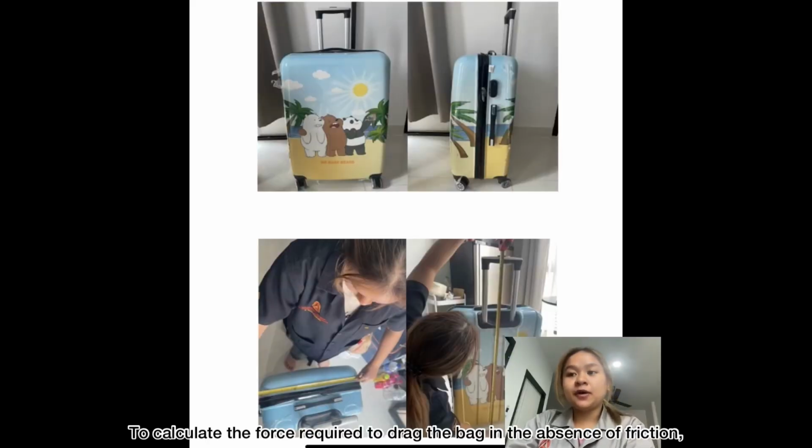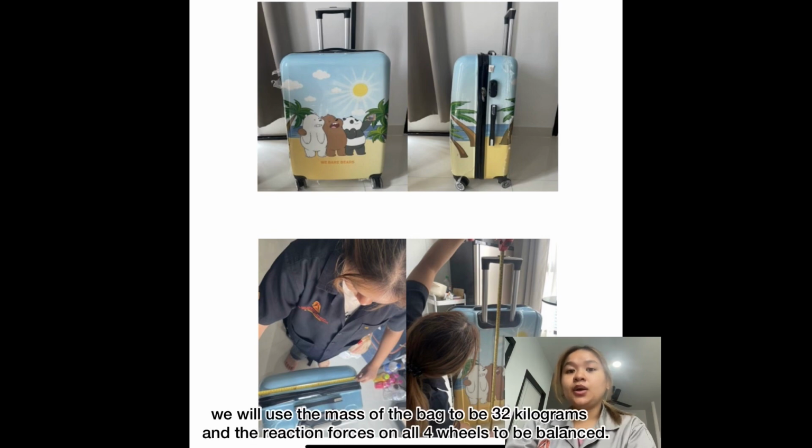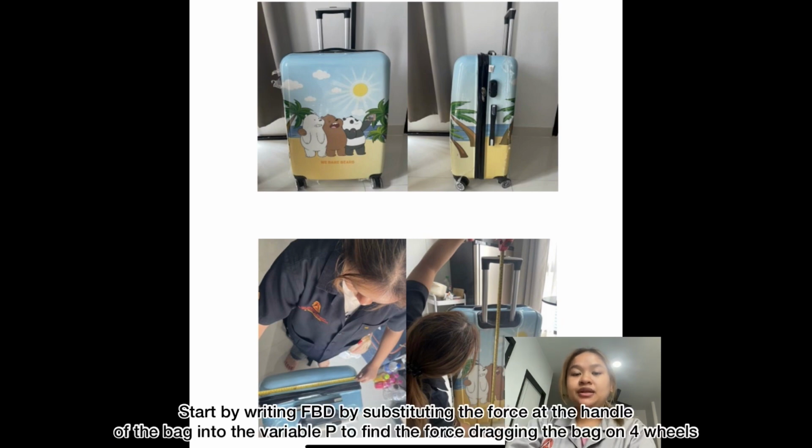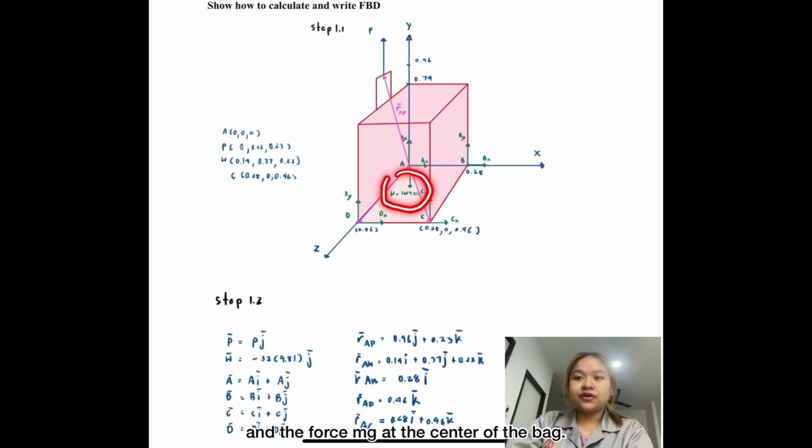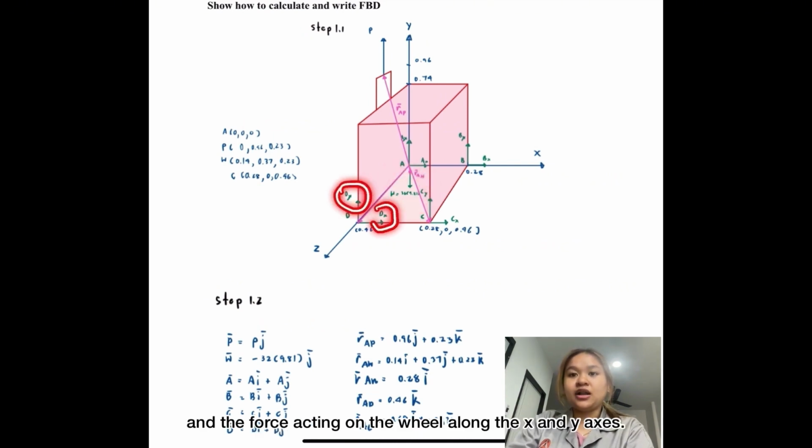To calculate the force required to drag the bag in the absence of friction, we will use the mass of the bag of 32 kg and the reaction force on all 4 wheels to be balanced. Start by drawing the free body diagram, substituting the force at the handle of the bag with the variable P to find the force dragging the bag on 4 wheels, the force mg at the center of the bag, and the force acting on the wheel along the x and y axis.